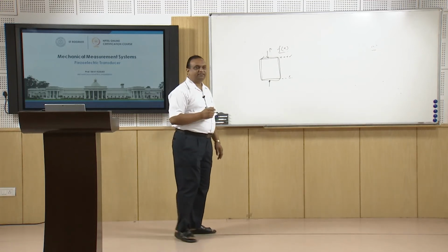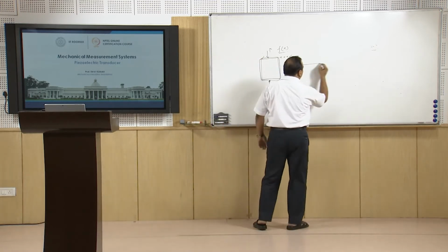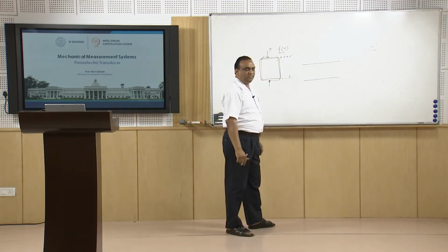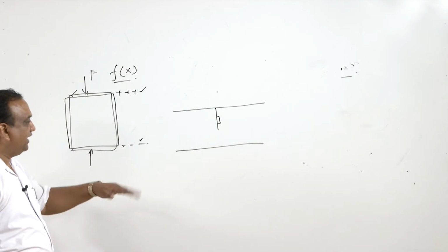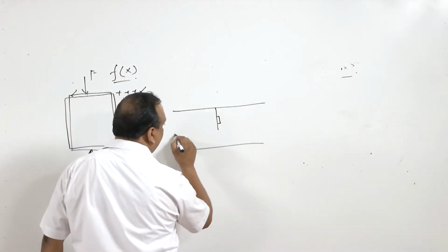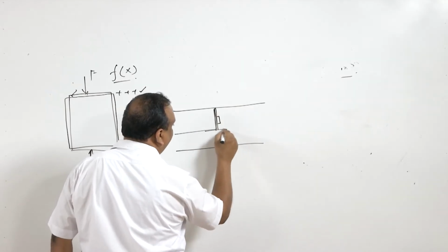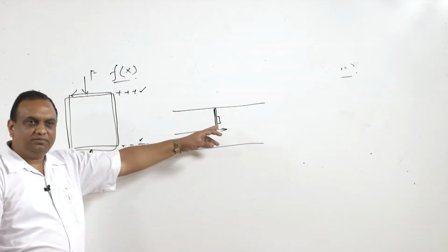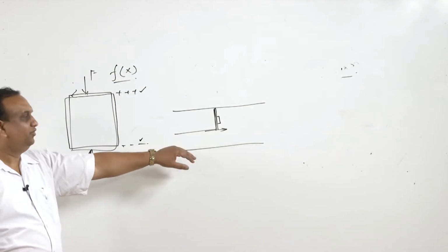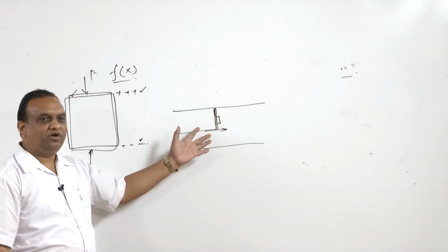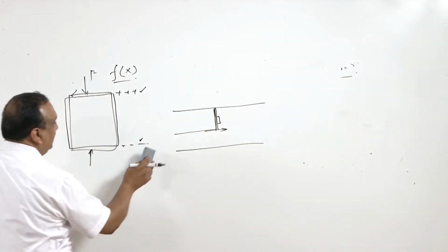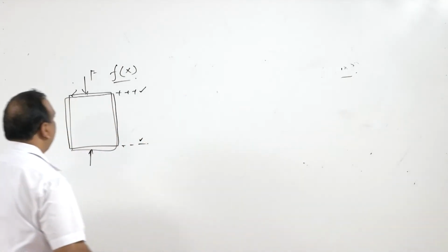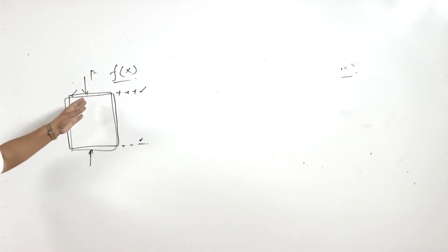Now, for example, let us take example of a strain gauge. Suppose there is a flow in a channel, right? And if we insert a vertical with strain gauge fixed, and this is a flexible type of thing. So, this fluid will push this cantilever in this direction and strain will be developed. So, not only strain gauge can be used for measurement of the strain, it can be used for the measurement of flow as well. Similarly, here for piezoelectric transducer, not only they are used as a sensor for measuring the force or the strain, they can have variety of applications, right?